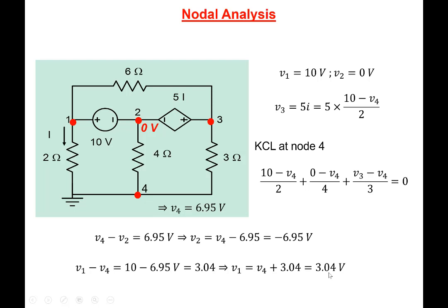So what this is saying is, even if a ground connection is given and you're not happy with this ground connection from the analysis point of view, temporarily you can forget about this ground and assign a reference node the way you want, the one which will help you in analysis. Do all the analysis, and you'll get all the voltages with respect to that node, and then you can transform it back to whichever reference was used earlier, right? So this is what we did here.